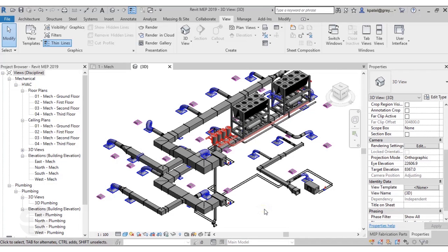The next new enhancement that we are going to focus on is related to the parallel pump analysis. Now we can add or remove pumps in a mechanical equipment set operating in parallel conditions. When we create a mechanical set, we can specify the number of on-duty pumps and the number of pumps on standby. So let's see an example here.